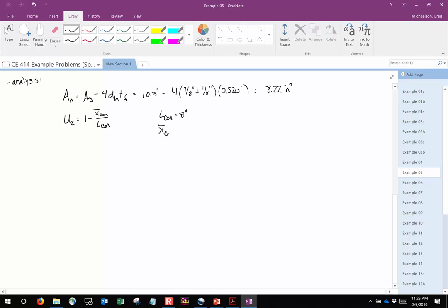So what about the X bar? What do we do there? We need the Y bar for a what? A WT 6 by 17.5. What is the Y bar for a WT 6 by 17.5? 1.3. Is everybody able to find that? Remember, this is the special case for W shapes. When you have W shapes connected via the flanges, you turn it into an equivalent WT. This is the only time that you do that.